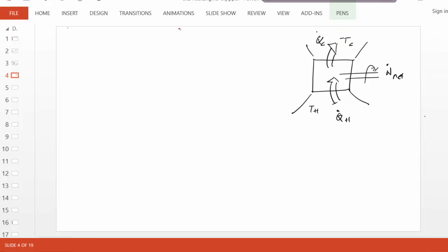So this is the new plan of a heat engine. Let's draw a boundary around the black box. Once again, it's a very simple definition of a heat engine: heat enters the system at a temperature TH that remains constant, and produces shaft work, and heat is rejected at a temperature TC, which is typically the atmosphere. So this temperature is known most of the time.